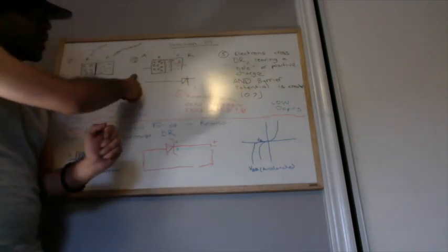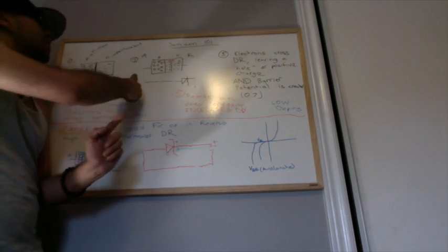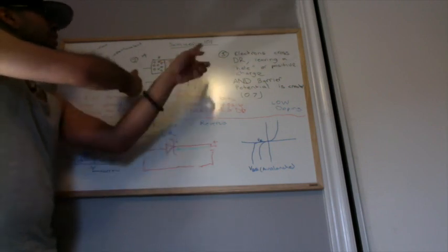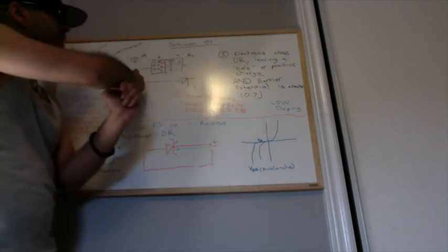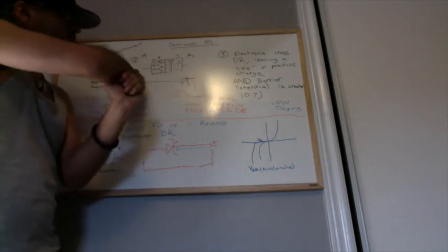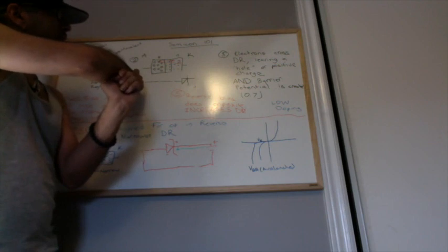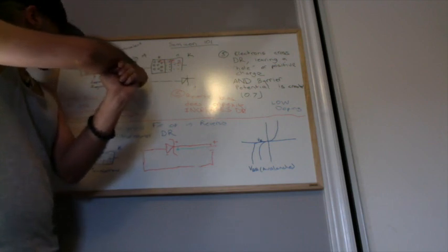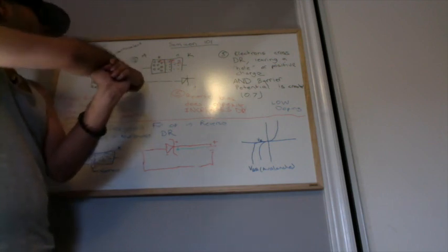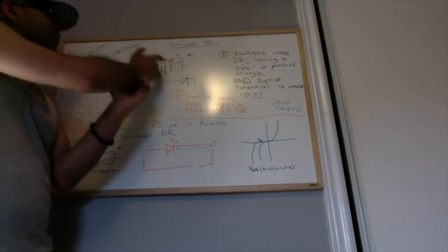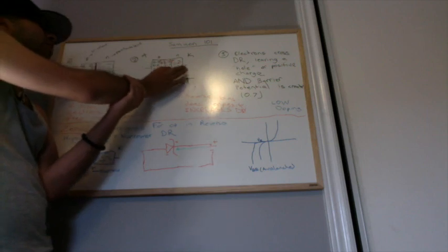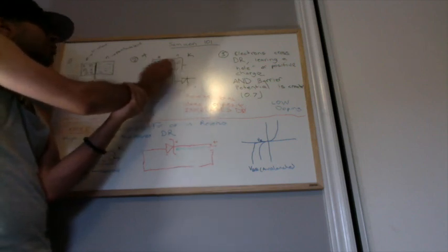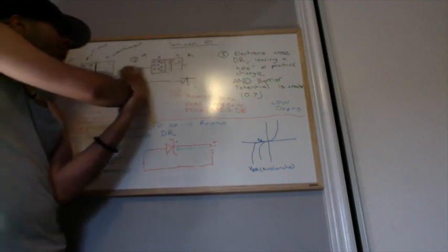If you had positive side connected here, negative side connected here, what would happen is eventually in forward bias you get rid of the entire depletion. You pass the barrier potential, meaning there's no depletion region, or it narrows very much so, and you're passing current.